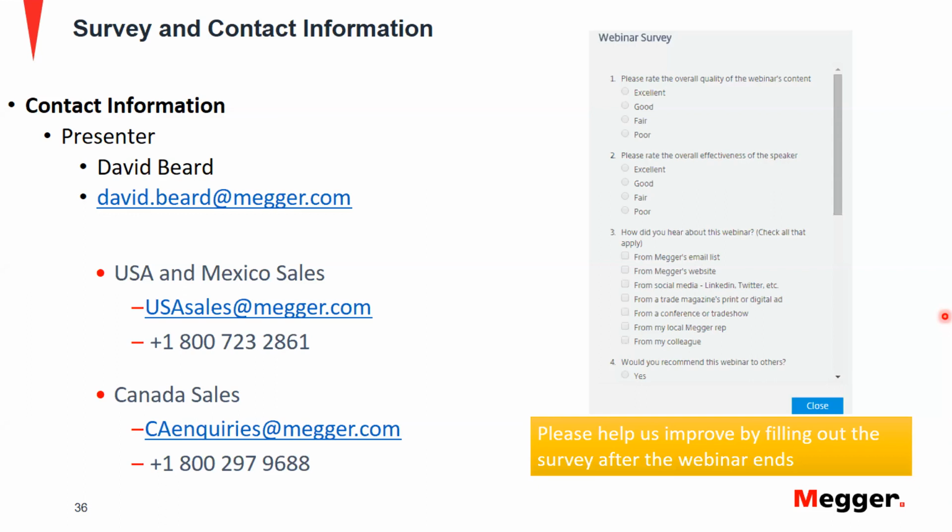Once you get that run, it gives you an option at the top by the report that says add to report. If you're in the timing screen or one of our predefined screens, like a transformer differential screen or a state sequencer, then those automatically populate that test into a test file. And going into the T with the lightning bolt would give me my different tests and allow me to group those tests how I see fit.